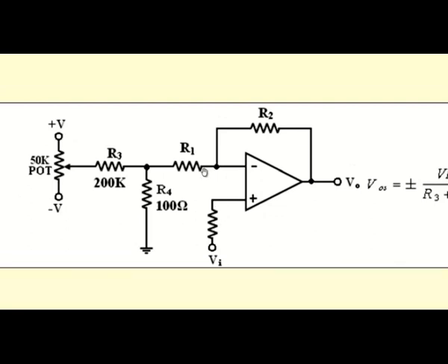If the offset pins 1 and 5 are not used, as it is not given in some integrated circuits, then we have to externally compensate the output voltage, make the output voltage 0 due to some imbalances present in the circuit, by applying input offset voltage at the input pins. If the inverting terminal is used for the signal, then the balancing circuit is given for the positive terminal. Similarly, for the non-inverting amplifier also.